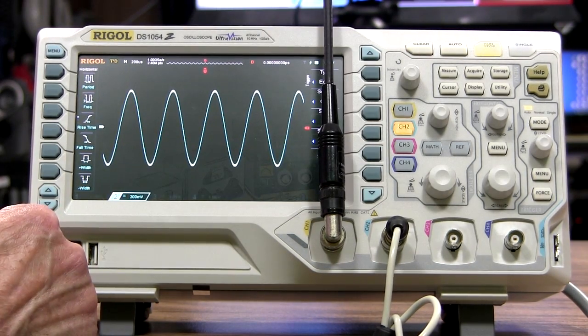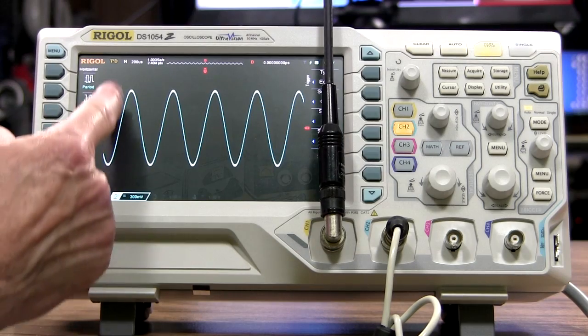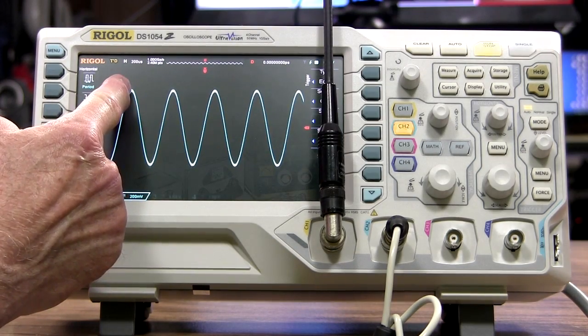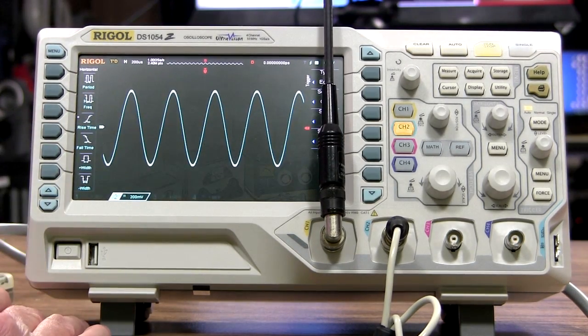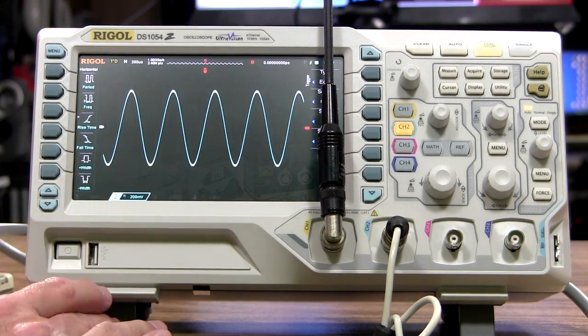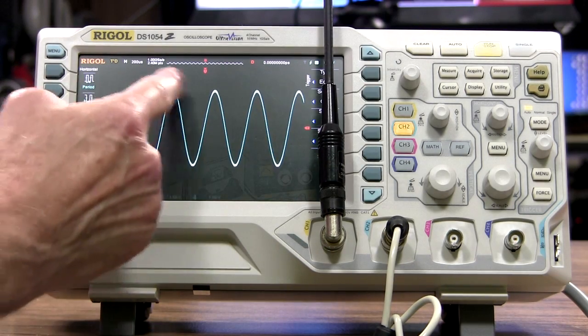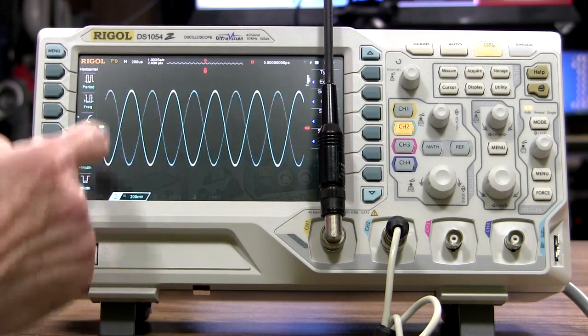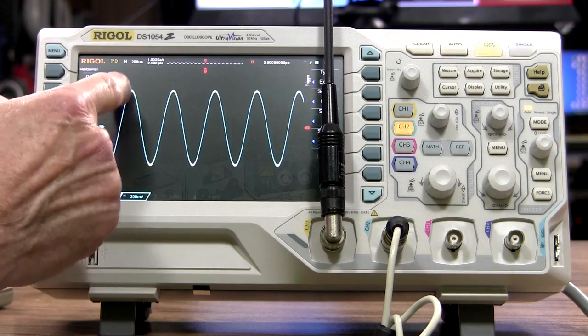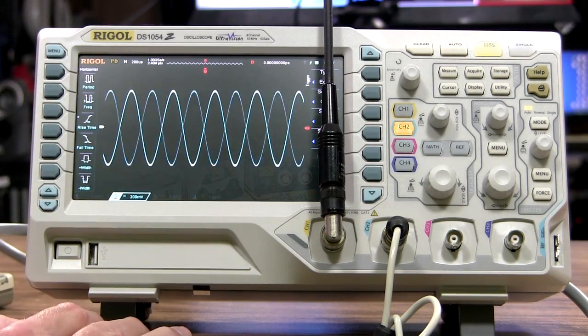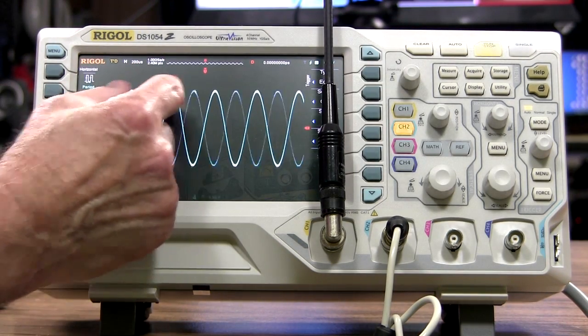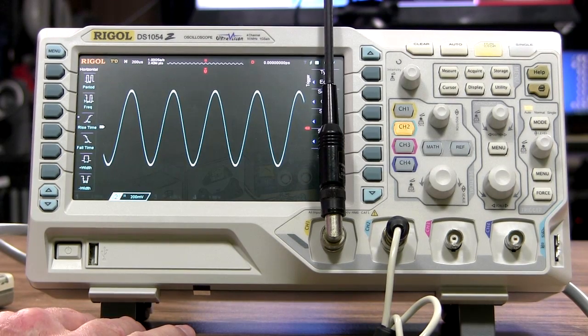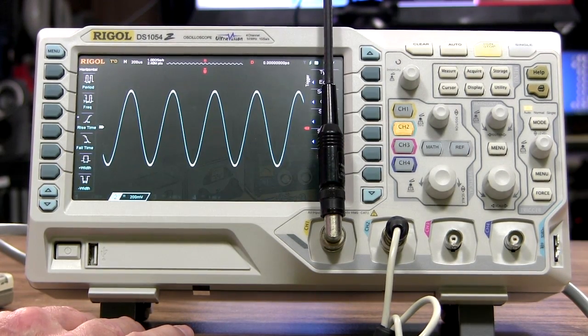As Tommy mentioned earlier, to check a wavelength, you'd measure from the top of one waveform to the top of the next one right there. And that would be your wavelength. On this scope, you can put markers, or what they call cursors, that you can mark one spot and then slide it over and mark another spot. You can measure the distance between those two, but it gives it to you in time rather than a wavelength. Then you could calculate it out from that.